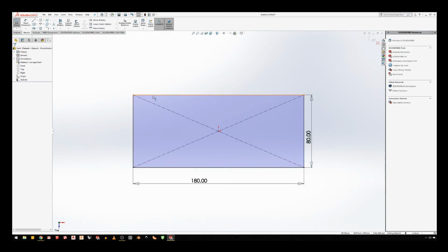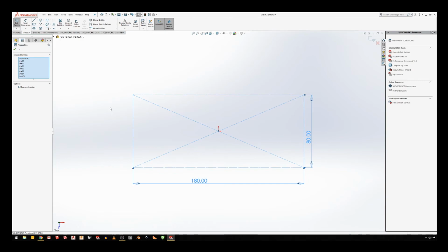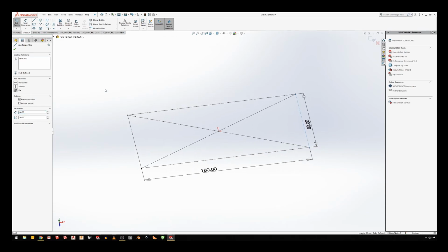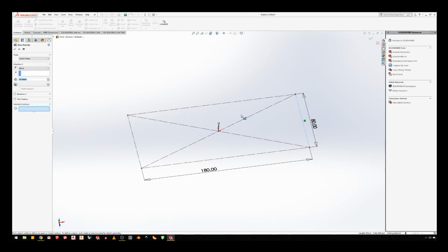And let's highlight this whole thing and just make it for construction. So now you can see all the lines in here are constrained, but they are construction lines, so they'll be completely ignored. As you can see, the feature tool extrude will not do anything because it's unrecognized as a volume. It doesn't see any contours, anything like that.